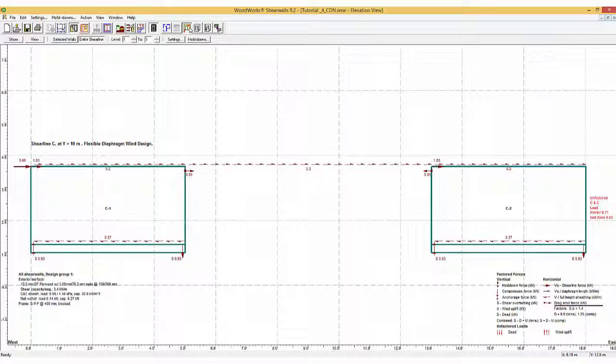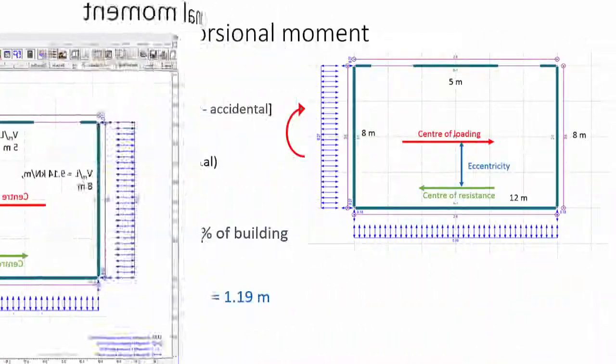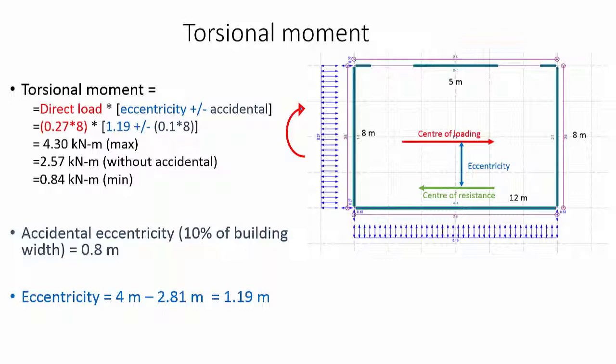A rigid analysis accounts for shear forces due to relative stiffness of shear walls and the torsional behavior of the rigid floor diaphragms. The torsional eccentricity is related to the distance between the centroid of the applied design load and the center of rigidity of the shear wall. An accidental eccentricity is added or subtracted from this distance to account for uncertainties.